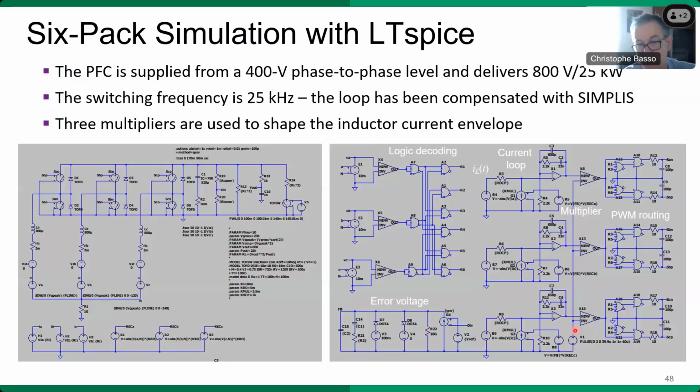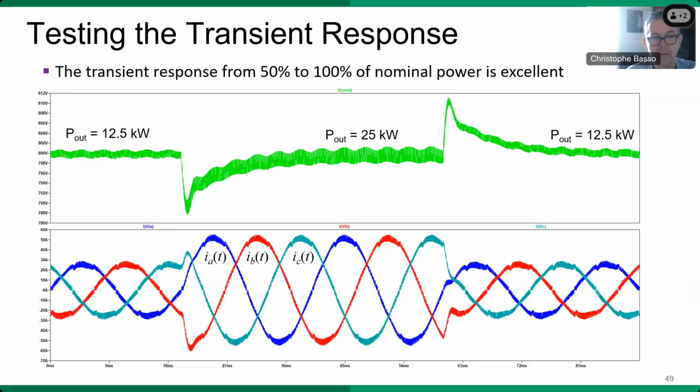This time with three-phase PFC, you're no longer constrained to have a low crossover frequency at a few Hertz, an inherently slow type of response. With three-phase, you can push crossover slightly higher. Here I was able to meet 100 Hertz crossover frequency because of the lack of low frequency ripple. And the simulation here is good.